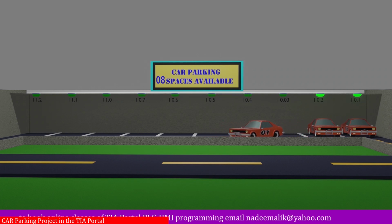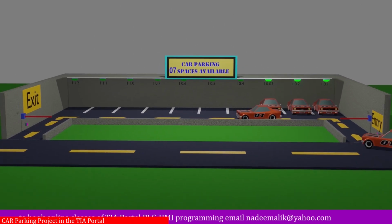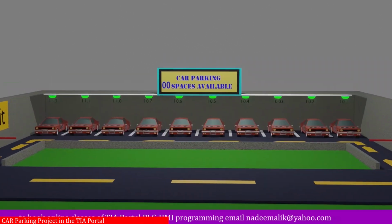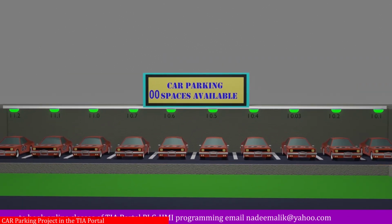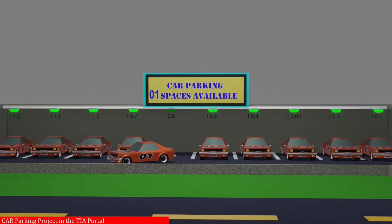Now we have to make a program in the PLC in such a way that it will track each parking lot, whether there is a car inside the parking space or not. And the PLC program should keep track of the empty parking space numbers, and we will show the number of the available spaces on the display. As the car leaves the parking space, the available space number should be updated immediately by the PLC program.